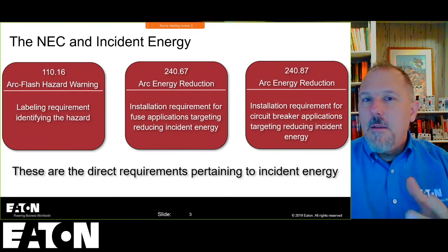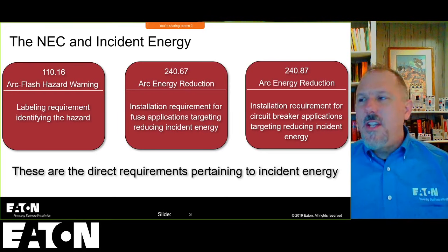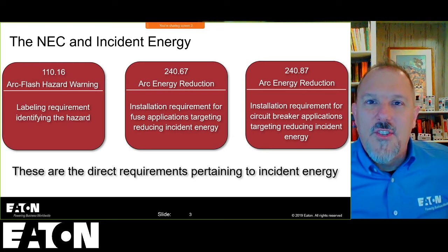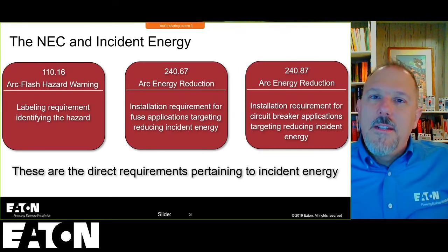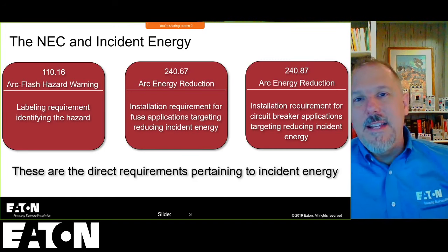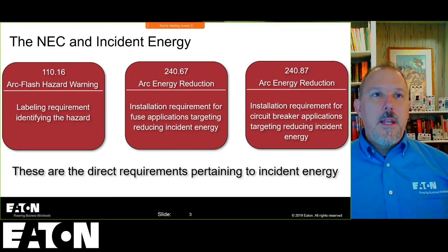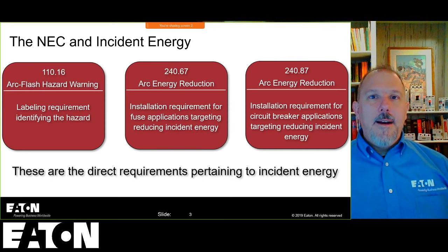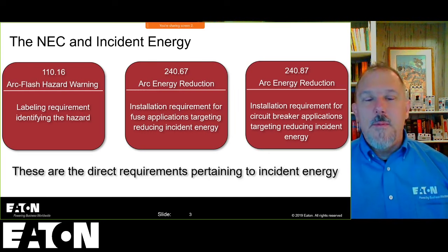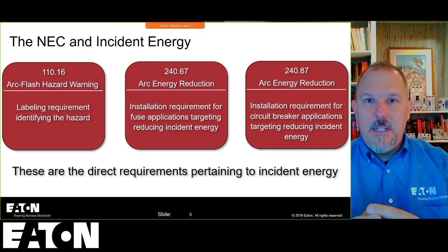And then I think probably somewhere down the road, there was an engineer who said, you know what, I'm going to ground one of the corners of this system because I've done my math. And I think we can live with a corner grounded system. They grounded one of the corners of that delta system, and they realized not only do I not have those severe voltage fluctuations, but I can provide a lower voltage leg off of this. Maybe I center tap or whatnot. Well, they shifted the issue though.